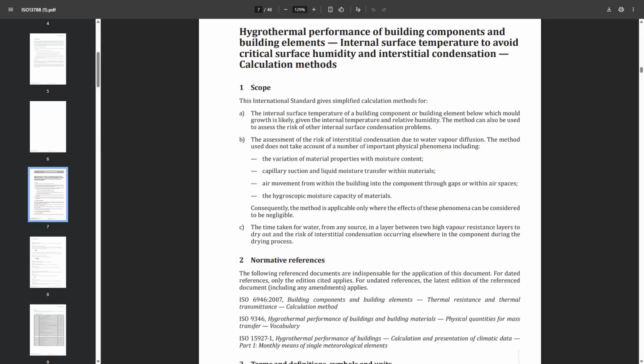I'm not suggesting that you base all your design on this, but if you get something that you have fundamentally thrown lots of moisture into from a theoretical point of view in a calculation, and it works, then you're probably in a position where doing something more complex and detailed in a dynamic hygrothermal simulation over 10 years, for example, would probably work as well.